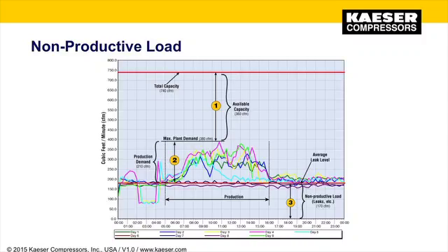Approximately 170 CFM, 50% of the productive load, was simply being wasted. This is the equivalent of running 40 horsepower worth of compressed air all the time. This customer was spending over $20,000 in electricity with absolutely no benefit from the compressor running, not to mention the additional maintenance for this particular machine. Unfortunately, this is not uncommon and occurs in much larger systems as well.